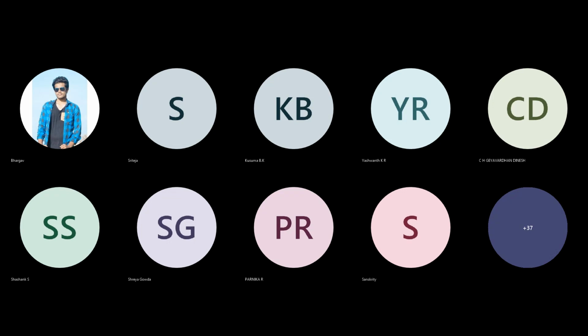xf is A beta divided by 1 plus A beta times the input signal, and A beta is greater than 1. We see that xf is almost equal to xs, which implies that the signal xi at the input of the basic amplifier is reduced almost to 0.